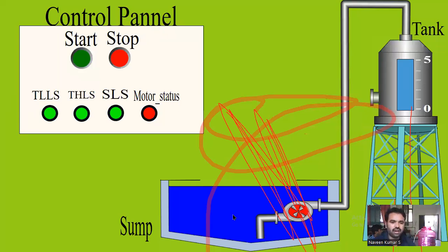They may ask how this reservoir system can be controlled and monitored through this SCADA screen. We will be using solenoid valves there to open and close the gates. In such cases, the water level from the dam can be seen on the screen. At various levels, we will be keeping the sensors that can be seen here, and based on that water level sensor, we may need to open some gates in the dams.